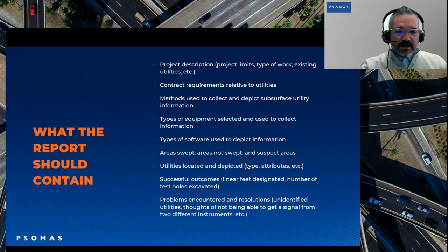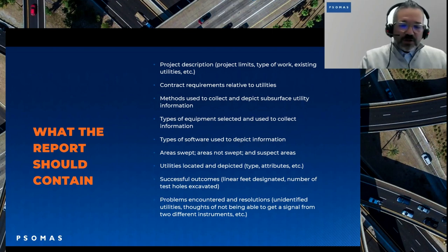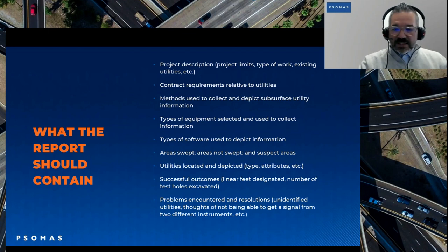There's a lot of software out there within the equipment and then within the post-processing in order to develop the report. What areas did you sweep? Areas not swept? Suspect areas, where do you see challenges? What utilities did you locate and what is depicted? What type, what attributes? All of this can be defined within the report itself. Successful outcomes, how many feet were designated, number of test holes excavated. All of this should be contained within that report.